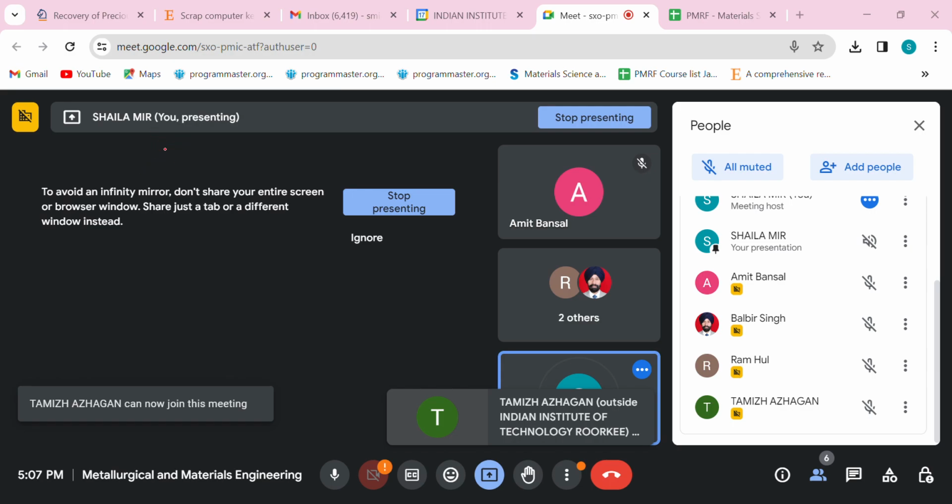They are an important and crucial component of renewable energy sources. Your wind turbines have rare earth magnets. Your hard disk drives also have rare earth magnets. So these permanent magnets are hard magnets, and they are of these types: ferrites, rare earth magnets. They have some formulations like Nd2Fe14B. This is a type of alloy that is formed for these magnets, and it behaves as a very hard magnet and is used in various applications. It is called rare earth because Nd is a rare earth element. So this is utilized in these applications.